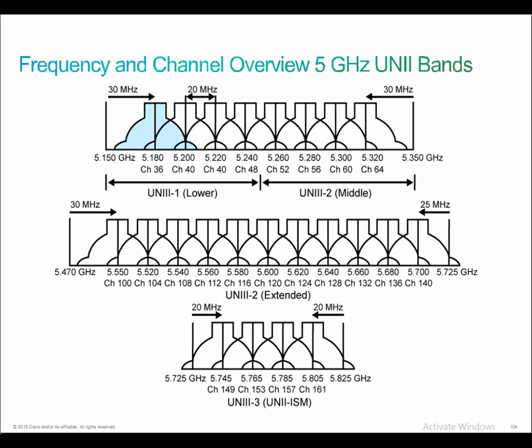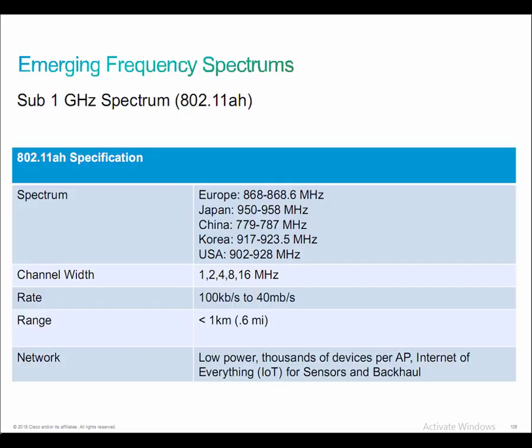Now there are some additional schemes available today where we're not dealing with 20 megahertz wide channels anymore. We're dealing with 40 megahertz wide channels, and there are all kinds of ways of utilizing and managing these channels to provide additional features. We might get into that in this chapter. I know we do talk about channel aggregation a little bit later on. I'm pretty sure of it. Probably a few slides from now.